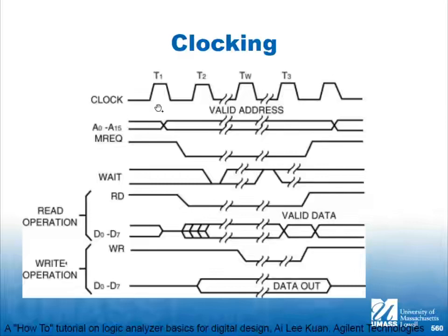But I would use up a lot of samples because I have to at least sample twice as fast as these signals are changing. So I have to at least sample twice as fast as this clock, which means I'm wasting a lot of samples. And the sampling rate isn't continuously variable, so it's probably more like at least 3 times the clock rate.